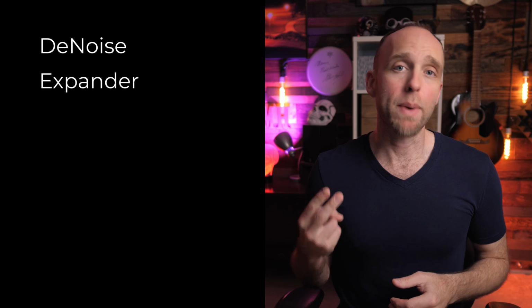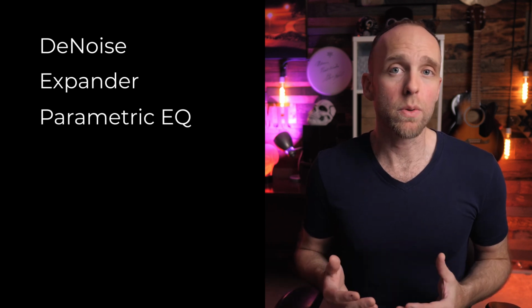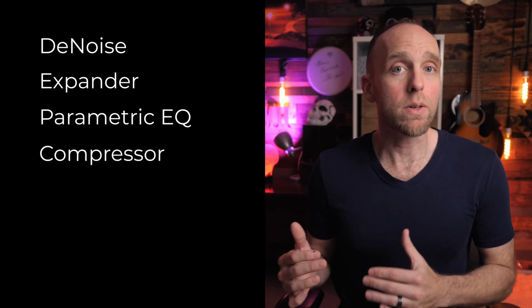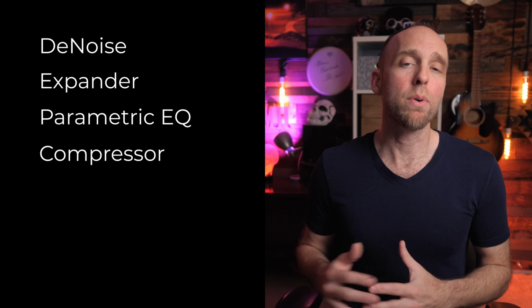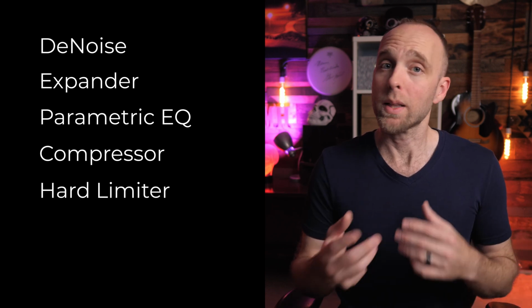All right, so to recap, make sure you record your audio into your camera or computer at a strong level to get it above any noise in your system or in your camera. Then what I do is I denoise. I expanded the signal to make the quieter parts even more quiet. Then I EQ'd the signal to what I thought sounded better. And then I compressed the now cleaner EQ'd signal and then used the output gain of the compressor to get the overall level and loudness up. Then I made sure I wasn't clipping anywhere.